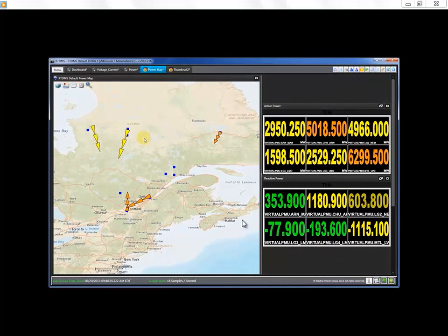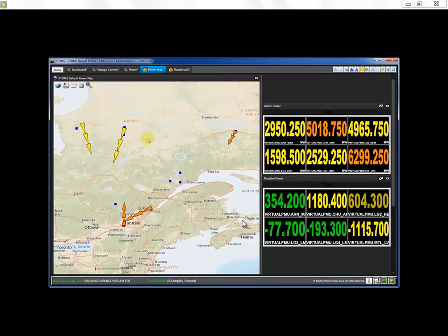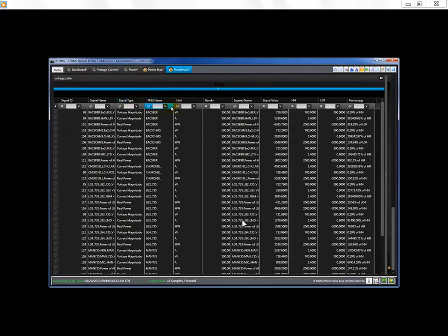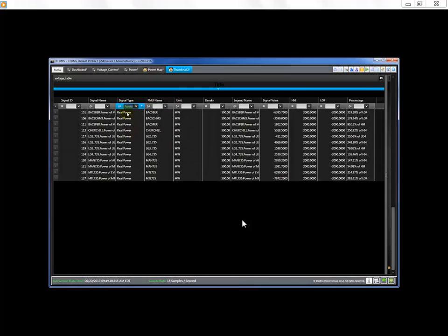So we have some blocks inside our RTLab library that allow a signal to be given to the block and be made available to the world as a PMU. We then have a Phasor Data Concentrator that we connected to those PMUs, and that Phasor Data Concentrator is sending data to RTDMS, where you can visualize all of it.